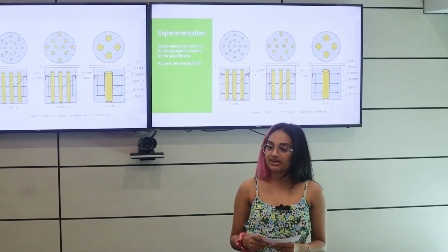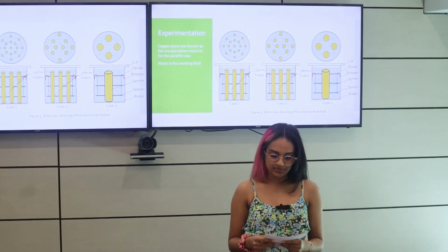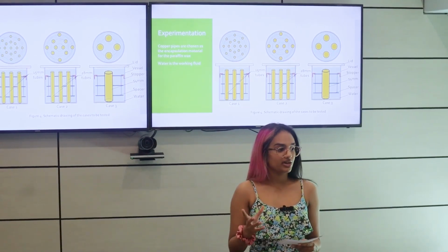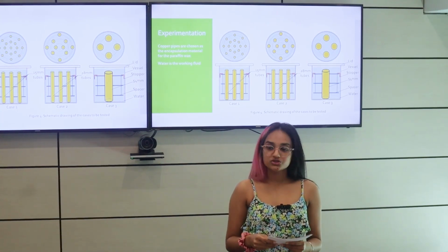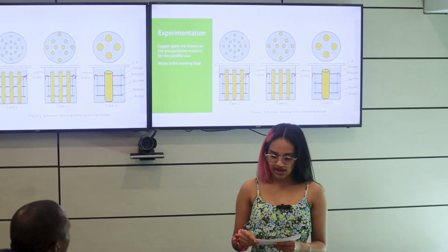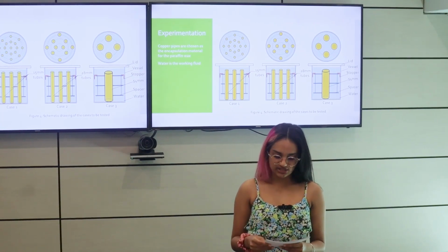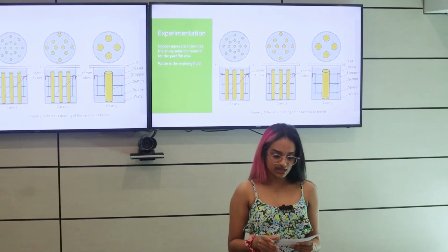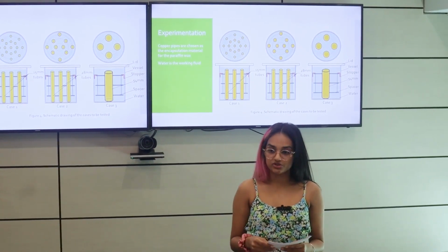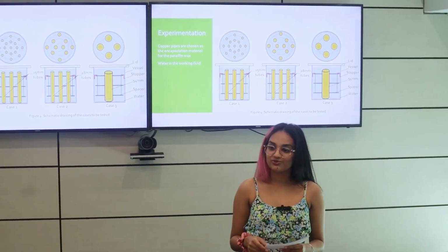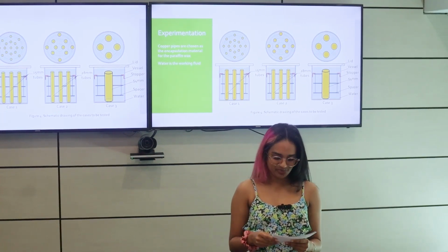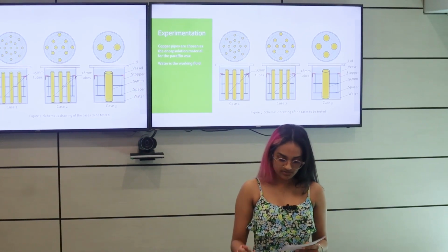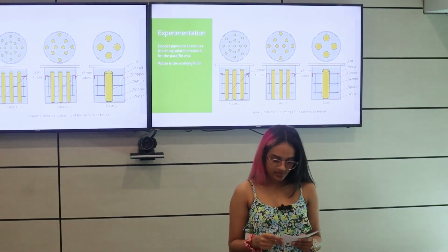It is vital that the wax and water do not mix. Thus, I chose to encapsulate the wax in copper pipes, which I sealed with copper end caps. In order to quantify the effect of the wax, I decided to have 3 different cases for testing and comparison. Across the cases, I kept the exposed surface area of the copper tubes at 2,543 centimeters squared, but varied the amount of wax per case. This was done, as you can see here in figure 4.